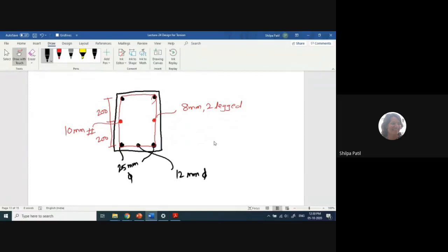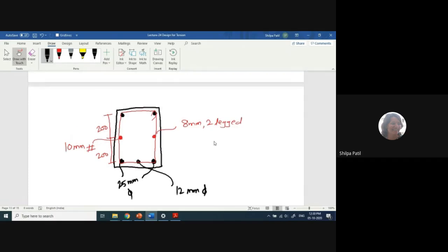Normally, minimum reinforcement we provide in the compression zone. The 12 mm bars are practically provided. So you can write down here 12 mm also, but our x1 calculation will be different now at the top and at the bottom. So to avoid that confusion, we will consider the same bar diameter here. Okay. Is it clear to everybody?